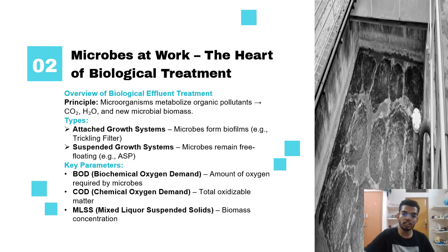The key terms involved in wastewater treatment by the microbes are the BOD, the biochemical or biological oxygen demand, that is the amount of oxygen required by the microbes to perform the oxidation of the organic pollutants, the COD, chemical oxygen demand, that is the total oxidizable matter present in the form of effluents in the wastewater, and MLSS, the mixed liquor suspended solids, that is the concentration of the biomass present in the wastewater.